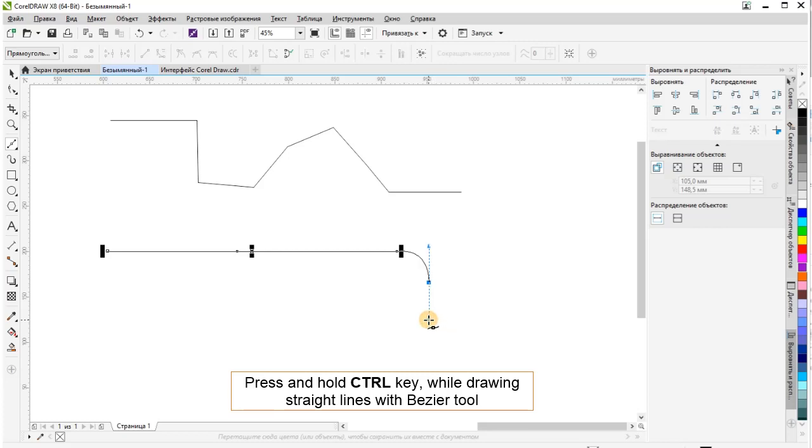By default, symmetric nodes are created. But if the user, at the time of releasing the mouse button, uses a modifier key, a smoothed node or breakpoint will be created. When the mouse button is released, the type of the node and the position of the direction points are fixed, after which the cycle for determining the next node begins. To exit the loop, press the space bar.